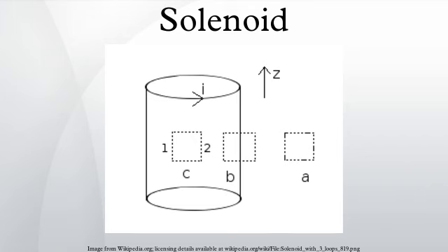Rotary voice coil. A rotary voice coil is a rotational version of a solenoid. Typically the fixed magnet is on the outside, and the coil part moves in an arc controlled by the current flow through the coils. Rotary voice coils are widely employed in devices such as disk drives. Pneumatic solenoid valves. A pneumatic solenoid valve is a switch for routing air to any pneumatic device, usually an actuator, allowing a relatively small signal to control a large device. It is also the interface between electronic controllers and pneumatic systems.